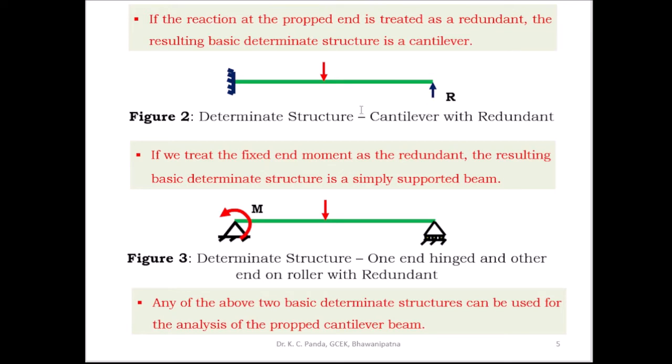Then in the second case, we have to remove the external loading, whatever it may be, a point load or UDL. Then we have to apply the vertical reaction at the propped end, in the upward direction. Then we have to evaluate the upward deflection at the free end.